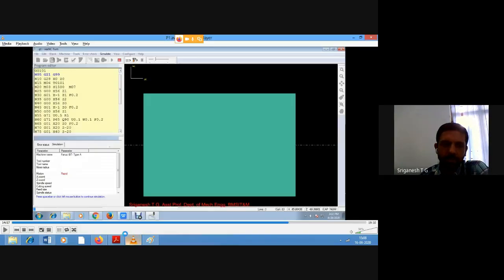Now, if I go back to this program, in the initial lines I have not used G94 at all. G01, G00, like this only for the facing operation. And I told you that it is called the uncanned cycle. But facing operation is also a repetitive thing, so we can do that. Why should I write so many lines? From N25 to N50, I am writing this only to remove 2 mm. So there is a cycle for that also, which has the code G94.